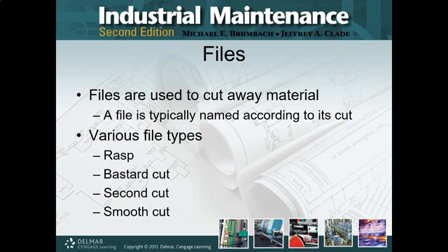Yes, it takes time. You let the file do the work. You don't push down on the material. You push across and through the material.